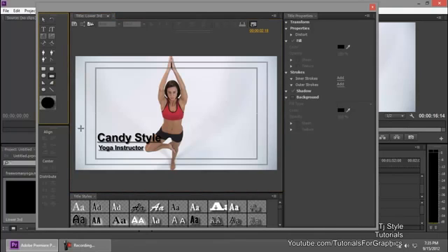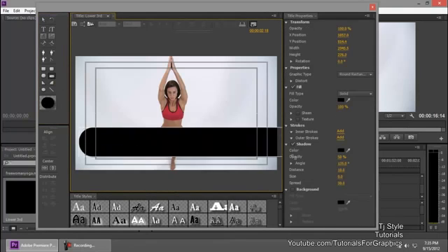Click on it and you'll see that you can draw a basic rectangle with cornered edges. Once you have created it, you can of course modify it. Using the Selection tool, just click on it and you'll see the bounding box appears. You can scale it down, you can make it fatter, or make it more skinny.